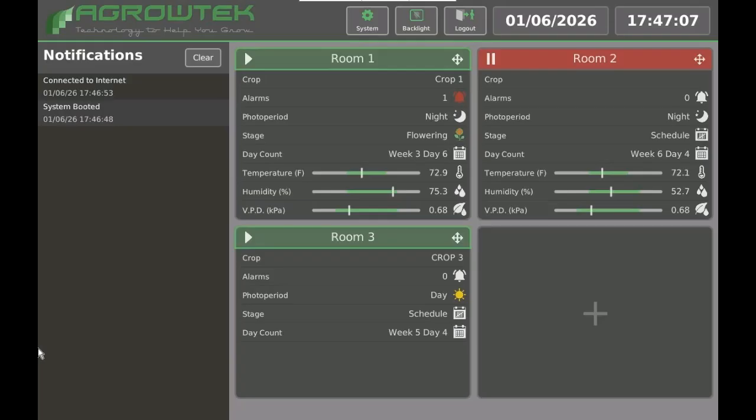Now, it's important to understand that devices have an internal memory, and in that memory, they will store an address number. The address number is how the controller will communicate with devices. So when the controller wants to send a message to a sensor to read its values or turn an output on relays, it will send a message to that address.